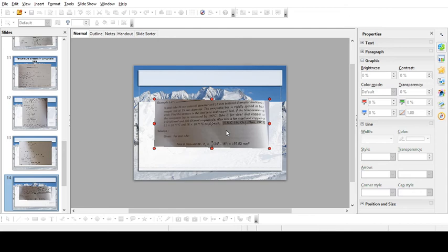Now let us find the required magnitudes. First, the steel tube is a hollow one because it has two diameters: the inner diameter is 18 and the outer diameter is 24. So the area of cross section of the steel tube is pi by 4 into external diameter square minus internal diameter square.